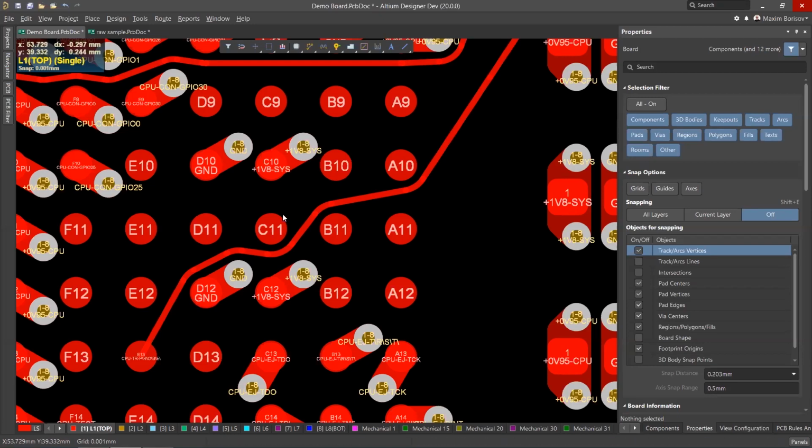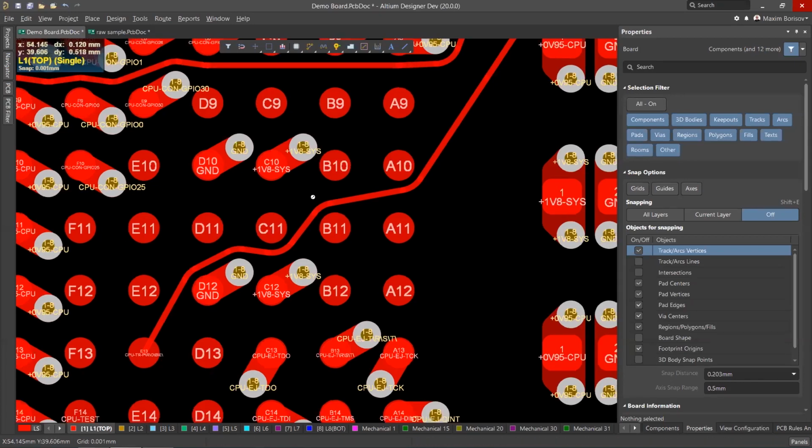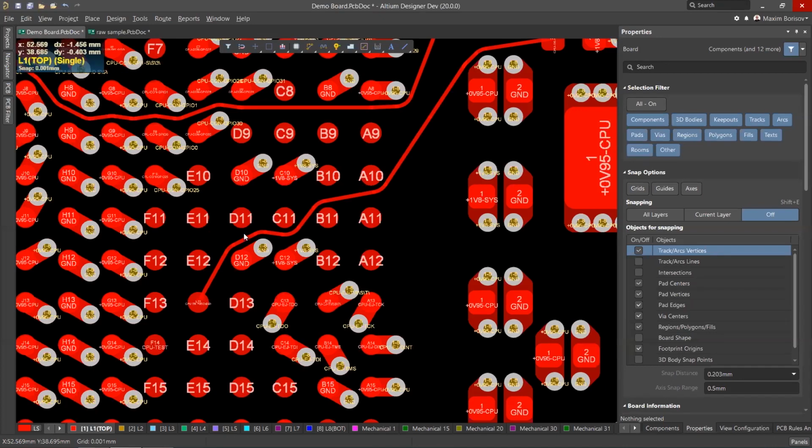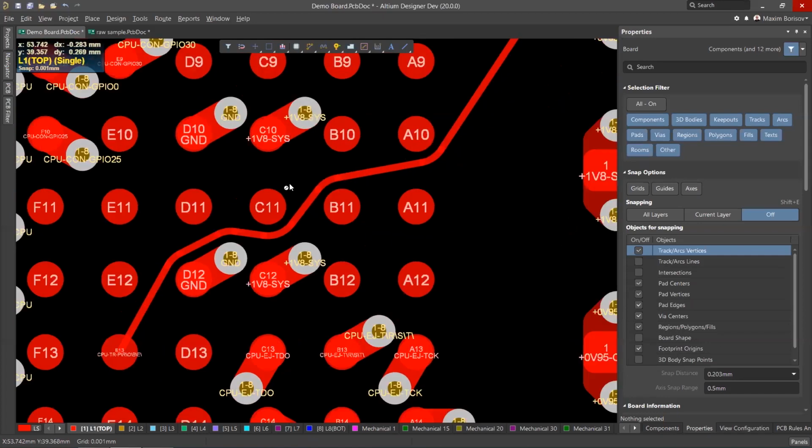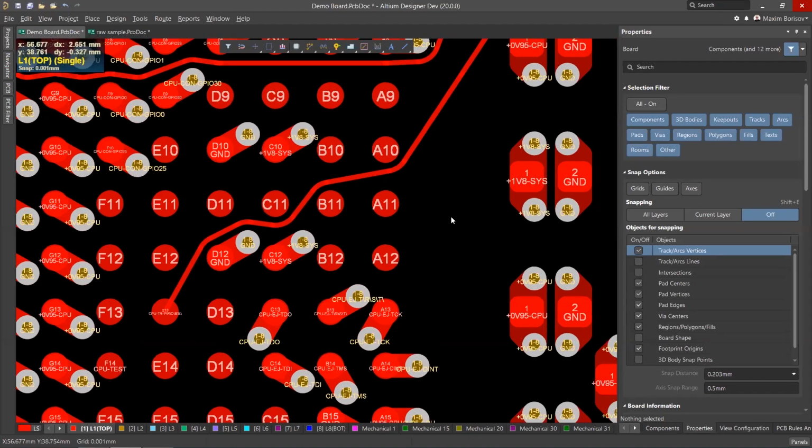It's a hard-coded value, which can only make a fixed length for the outcoming segment, which in such an environment will probably cause nothing more than DRC errors, because it's just impossible to place that value and maintain miters in turnovers, hanging all the paths, other zones, especially when you have a room here with one kind of definitions for clearances, for width, and on the edge, you'll probably get yet other artifacts.